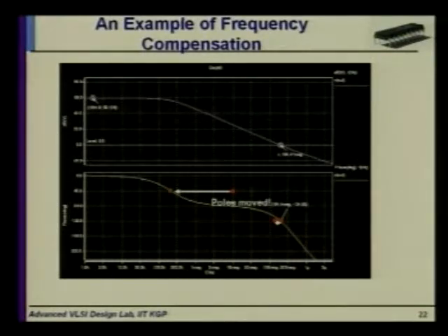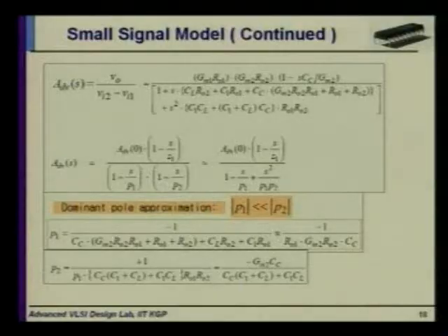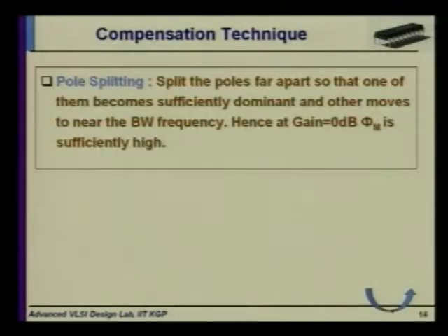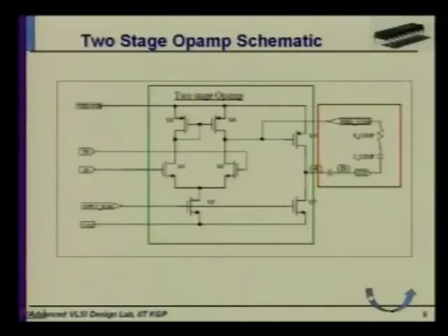I have given you a proposal, but how do we employ that in a real circuit? How do we realize that thing? We can realize it by using a capacitor, that is called a compensation capacitor. Okay, as you can see, this is the red area, that is basically for the compensation portion. I am not talking about the resistance right now, I am just talking about this capacitor. So we have introduced a new capacitor, that is called the compensation capacitor.